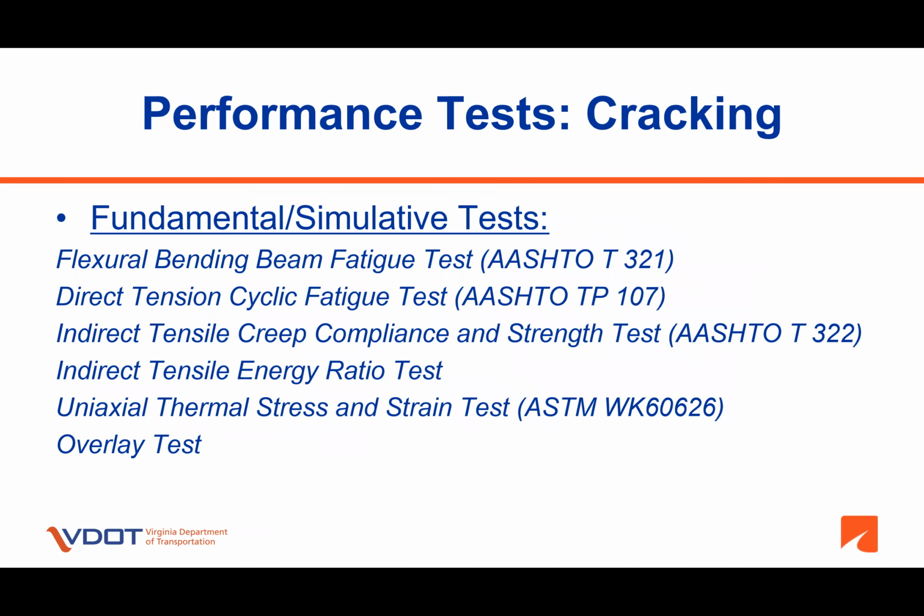To test the cracking potential of asphalt mixtures, we also have a diverse pool of test methods ranging from fundamental tests to monotonic loading-based tests addressing different cracking modes such as reflective, fatigue, and low temperature cracking. Fundamental and simulative tests are not generally favored by the agencies for the same reasons indicated for the rutting tests, especially for production level testing.